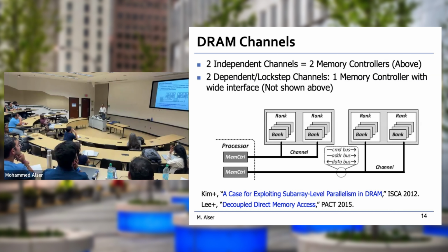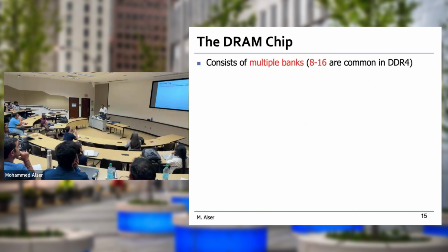Remember, whoever deals with the memory device is the memory controller. You can think of a memory controller as a program. It's really software. It's telling: activate this row, get me this address, give me this piece of information, and so on. So you can play with the order of that program and make something else. All right?